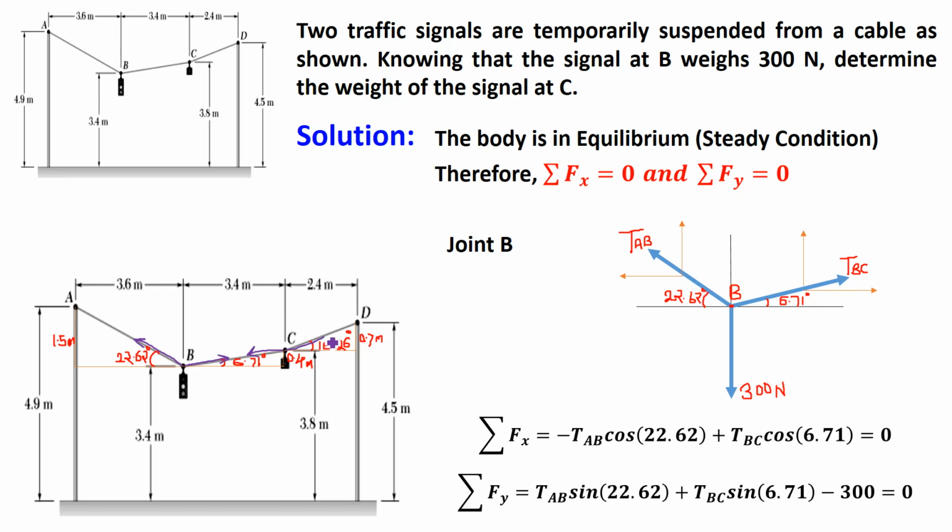You can show the tension in cable segments. So this is tension in cable AB. This is tension in cable BC, and this tension and this tension are the same. Then this is tension in cable CD. So please note, whenever cables are attached to a body, cables are always subjected to axial tensile force, which is going away from the joint.